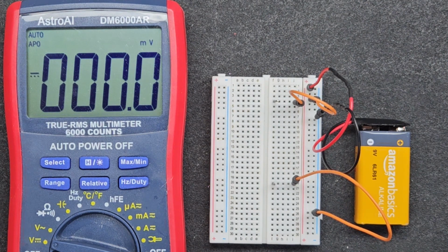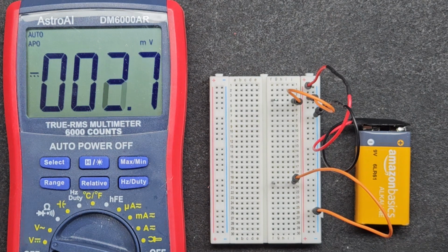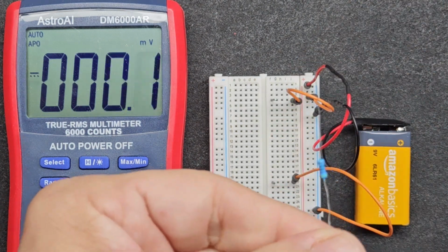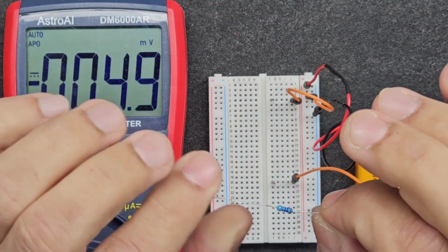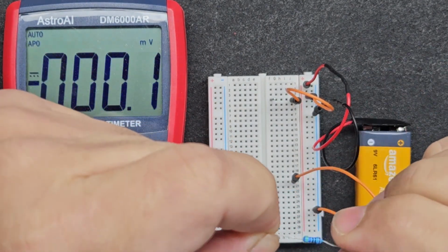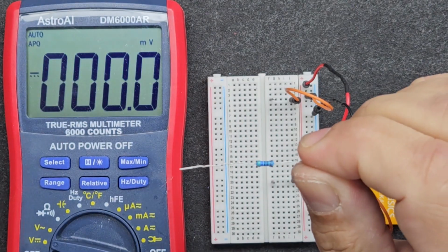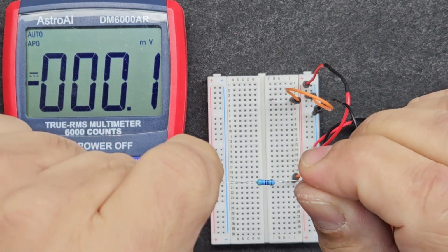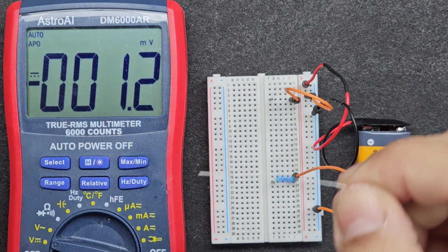Now from our example, we used an LED, shown here, which was 3 volts and 20 milliamps. And we had a 300 ohm resistor. Not sure if this is 300 ohms. Let's check. Resistors have these color bands wrapped around it. And given the color and the number of bands, you should be able to determine the resistance of the resistor.